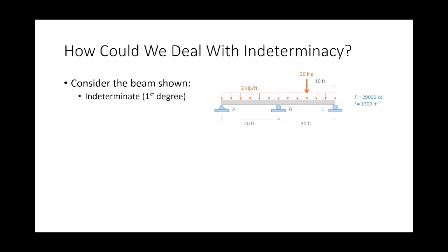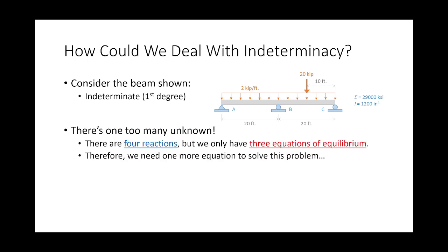So let's consider this beam. I just made this beam up. It's statically indeterminate to the first degree, okay? How many reactions do we have on this beam? 2 here, 1, 1, right? No internal hinges. So R is 4, E sub C is 0, R minus EC plus 3 is 1. So we have a structure that is statically indeterminate to the first degree.